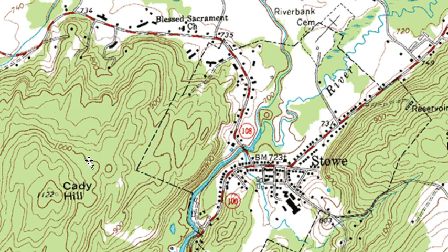Here's a map. Here we could see the contour lines, and they will be provided with an elevation. So here's 1,000 something, I don't know if we're dealing with feet or meters. So there's 1,000, here's 900, and then at certain increments they will make a darker line, so it's a little easier to read. And just by looking at this, we can't necessarily tell if these hills are going up or down, or where the highest or lowest point is, but we could definitely tell that there's a very steep area here, and up here at the top, these are more like plateaus.